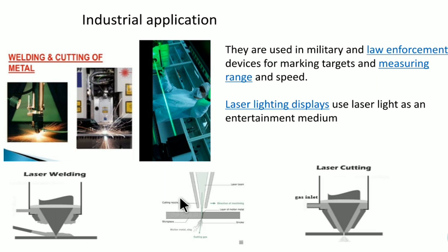Now come to laser drilling. Laser drilling is used for small holes in the order of 0.2 millimeter to 0.5 millimeter. Such types of drilling are not possible with ordinary drilling, so we can use laser light. That means they are almost used for industry purposes. Carbon dioxide laser, CO2 laser, is used here. Here, a very fine hole can be made. There is no problem of mechanical stress. As far as possible we can avoid the mechanical stress. Now these are some advantages as compared to ordinary drilling.